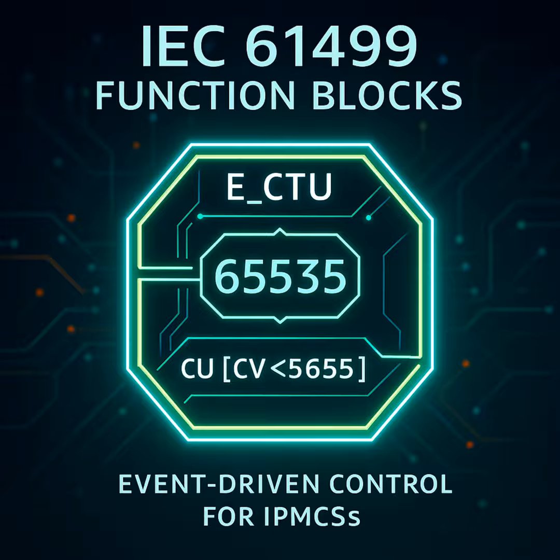Okay, let's start with the basics. What exactly is the ECTU officially? Right, so the standard formally calls it an event function block. That label itself tells you a lot. Event-driven, meaning it's asynchronous, it waits for something to happen. Precisely. It doesn't just run on a fixed clock cycle like older PLC logic. It sits there waiting for a specific trigger, an event pulse, before it does anything.